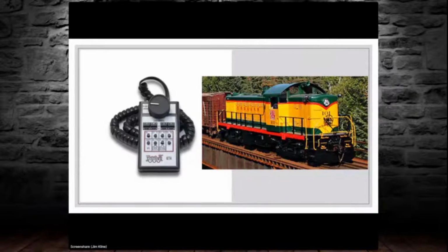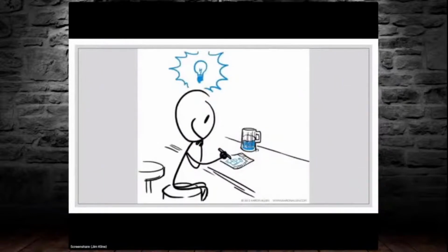It would have continued to run at that setting until it met an obstacle, derailed, or some other bad event intervened. The point is the decoder, in this case the microcontroller inside the decoder installed in the locomotive, will faithfully continue to execute its last instruction until told to do something else. Understanding that fact will help you to write code in a logical fashion, or if you're not going to write the actual program, be able to present to your programmer a specification that clearly defines what you want to happen.